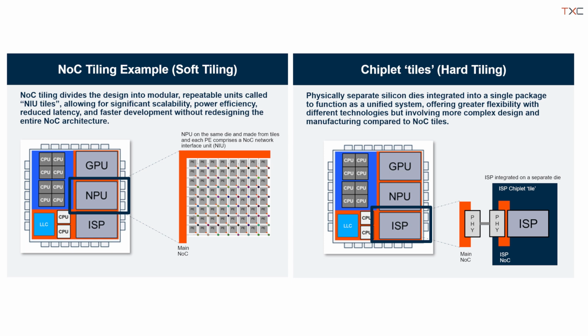Another concept of tiling is where you actually have a soft tile. So that's a replication of a piece of logic that exists in a design tool. You're able to take that piece of logic, define it, and repeat it multiple times in a modular fashion and replicate that out inside the design. Then the tool renders out that configuration, and that becomes the resultant RTL. So those are the two definitions that we're going to be talking about here today.